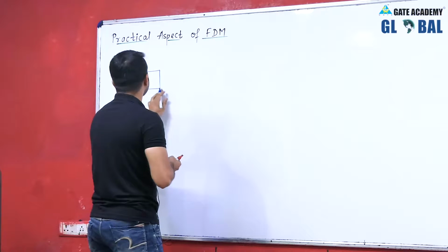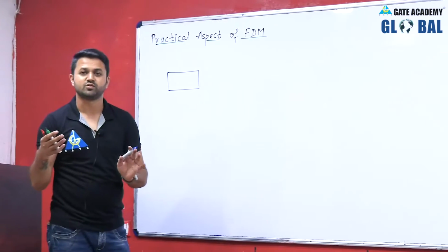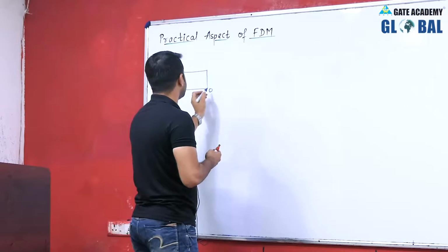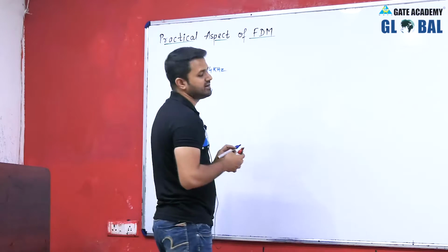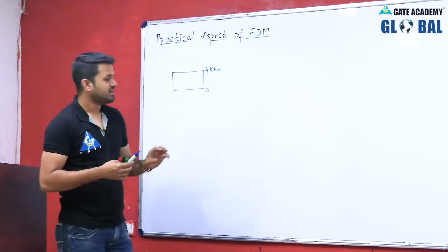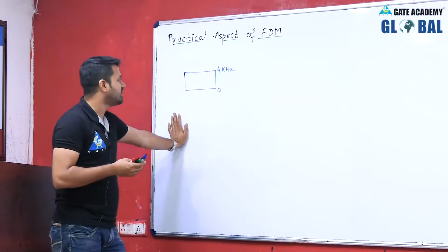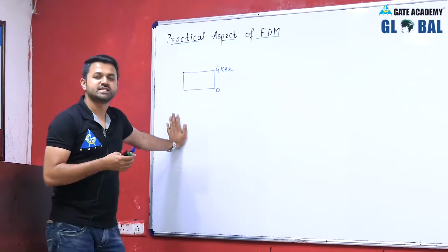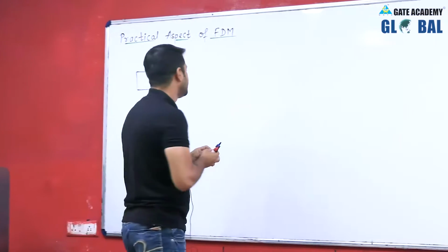which is our speech signal in case of frequency division multiplexing, because we are going to use the filter method. The range of this speech signal is actually 300 hertz to 3400 hertz, but practically it is considered as 0 to 4 kilohertz. Now, in practical FDM we consider 12 message signals together.